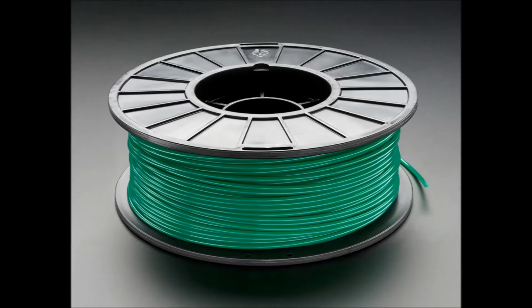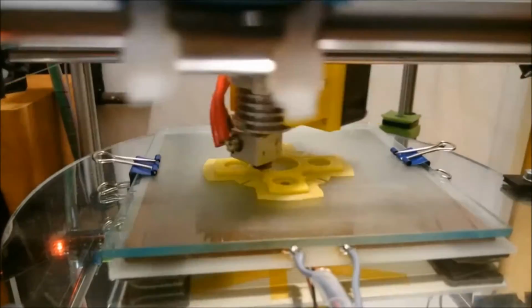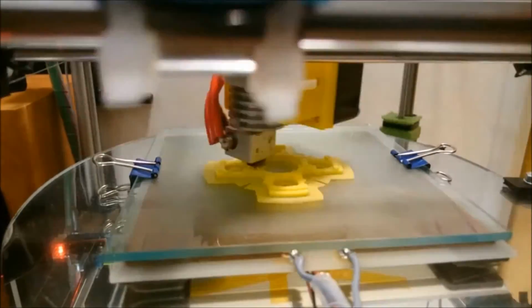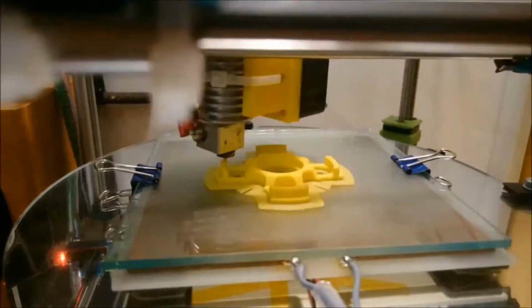It is introduced into a heating chamber where it melts and gets squirted out a nozzle. This heating chamber and the nozzle work like a syringe where the plunger is the solid filament entering one end, the liquid being squirted out the other end is the melted filament. This syringe-type hot end is then used as a computer-controlled pen, drawing an object layer by layer. The first layer is drawn onto a build plate, while the subsequent layers are drawn on top of the already cooled and hardened lower layers. Molten plastic sticks to the hardened plastic beneath, essentially fusing the layers together.